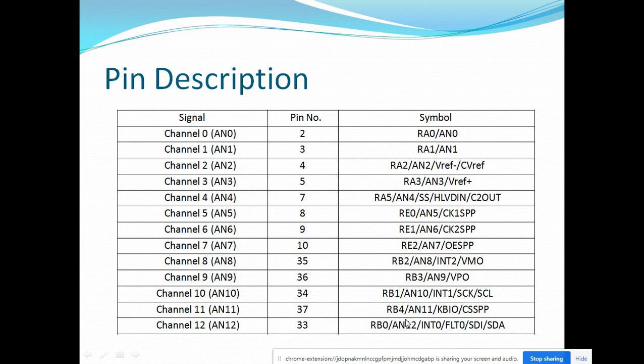Okay, these pins will act as analog to digital converter pins, and we can configure any one pin for one sensor. Okay, so in this way we can connect 13 sensor outputs to these analog input pins. Okay, so all of you know that it will have a 13 to 1 multiplexer. Generally we design 16 to 1. So here we can say that a 13 to 1 multiplexer is available inside this PIC microcontroller that connects 13 channels and converts these 13 channel inputs into digital form.